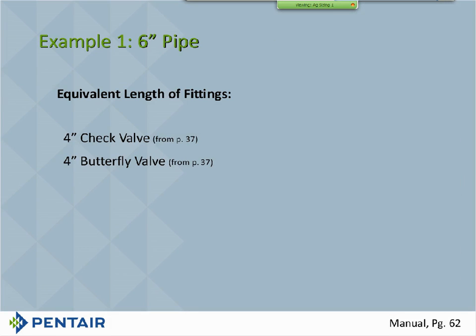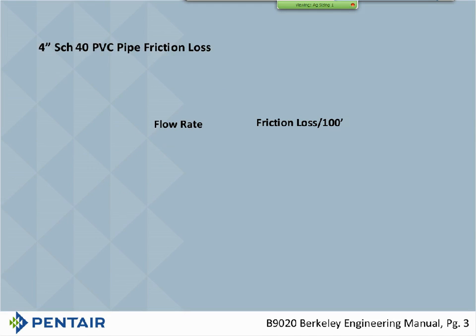So now we go ahead and we've plugged those numbers in. Don't forget you've got linear feet of pipe on the front side there. That first page, we had 2 feet, so 17 plus 7 plus 2 is going to equal 26. So our head loss now, to calculate it, we take 100 divided into 26, we get 0.26 times what? Well, let's calculate that out.